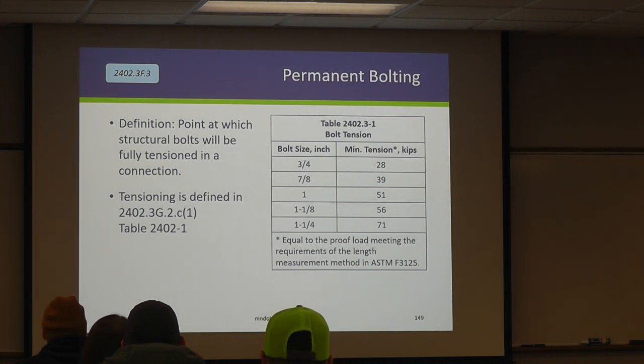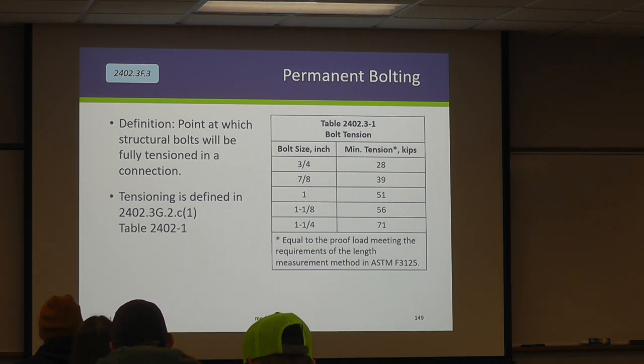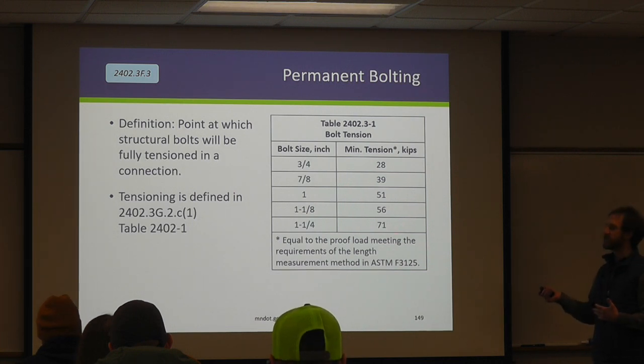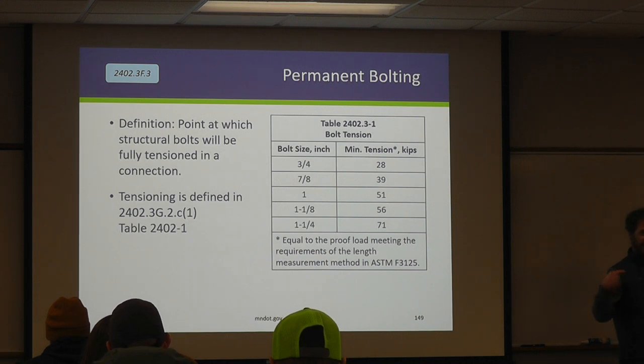Again, my slides get a little all over, it looks like. So permanent bolting. I've talked a lot about this. Again, this is that bringing it into its final geometry and strength for the rest of its service life. A bolt is defined as fully tensioned, permanently bolted, once it meets this minimum tension requirement in the bolt.